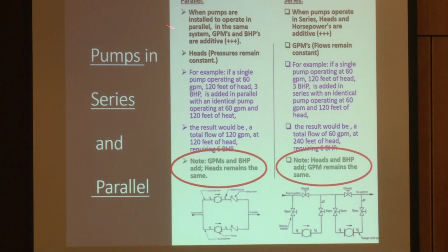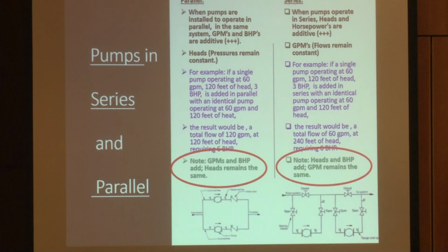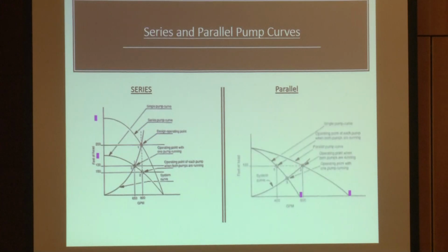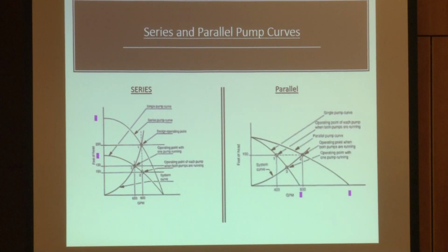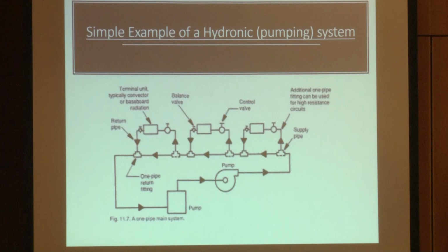And basically, we are almost always using pumps in parallel in HVAC&R. We rarely use pumps in series, very rare. I've only known a couple jobs in my whole life that I've ever seen series pumping. It's very uncommon, right? And of course, anytime you do anything with fans or pumps, you see the resultant series fan curves and the parallel fan curves here. Very common, very similar, right?